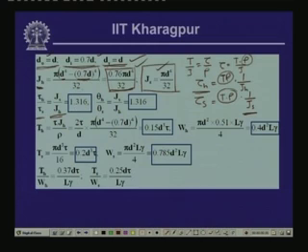And if you compute the ratio of J S to J H, you will find that this value comes as 1.316. Now, again if we take the ratio of the angles of rotation, theta H to theta S, and this is again T by J equal to G theta by L, hence theta is equal to T L by G J. Now, all other parameters T, L and G are common for both the shafts, both the hollow as well as the solid.